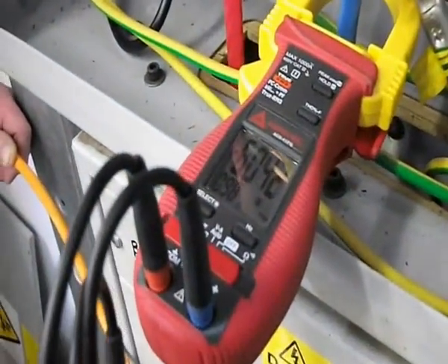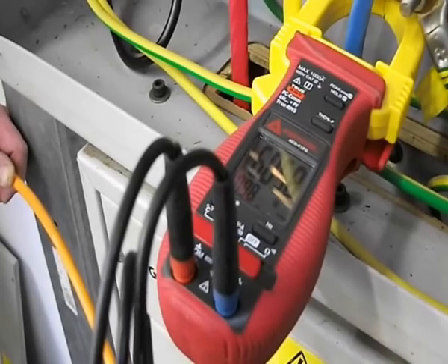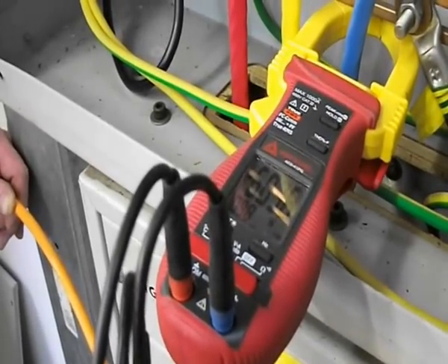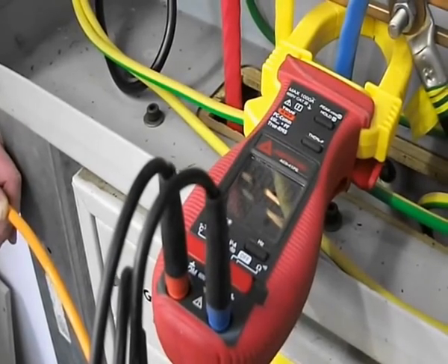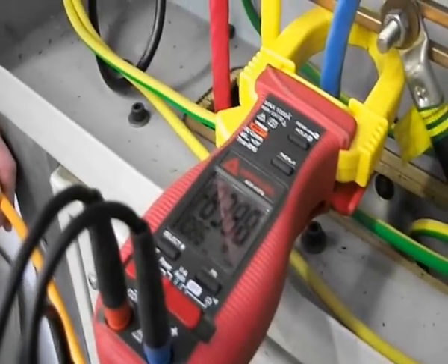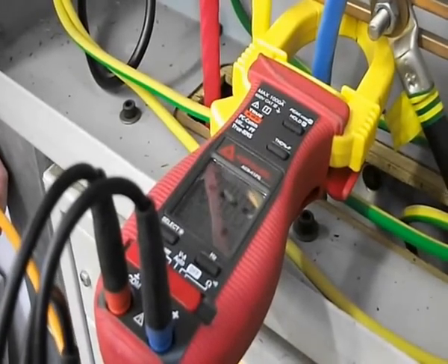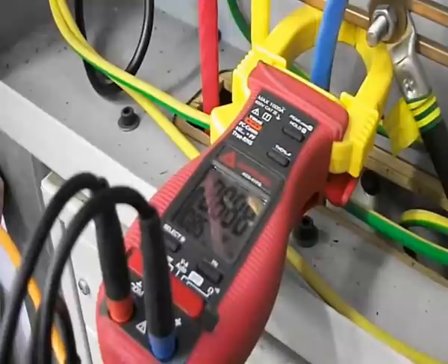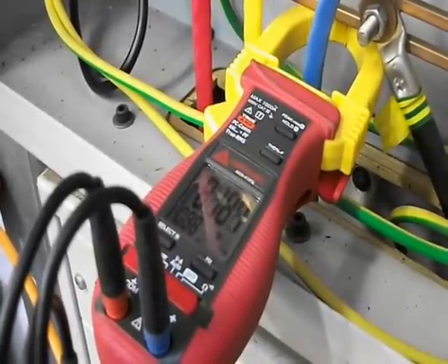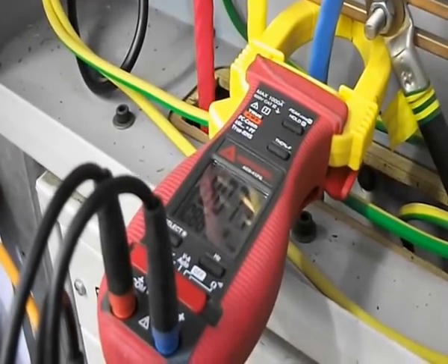Right, what I'm doing here is to record the power in this particular line, and as can be seen, the power is fluctuating continuously. The reason being that machines are going through variable loads all the time, and any increase in load on the machine will improve the power factor, and the converse is also true. But as we say, we've got no consistent power load. It's dependent entirely upon the loading on these machines, of which there are a large number.